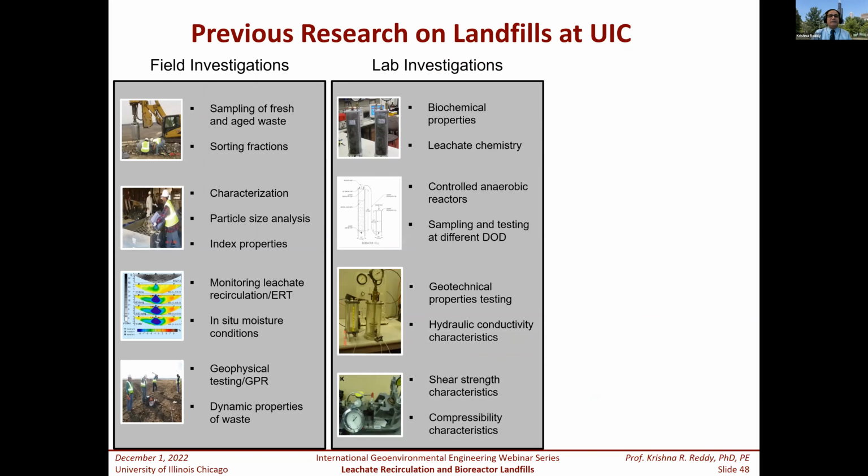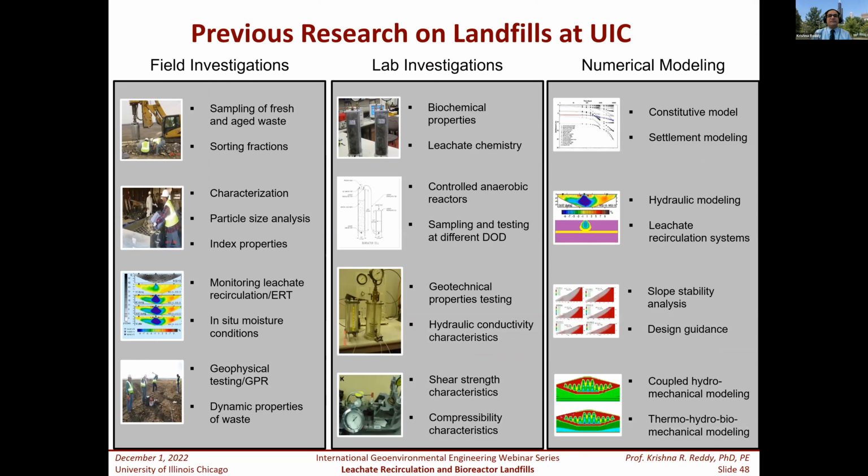In our lab, we have done a lot of field investigations. We did lab investigations. We did a lot of numerical modeling. I could talk about all these things forever, but I chose to talk only, in general, about what a bioreactor landfill is, and how it is different from a conventional landfill. I want to mention one thing again, okay? You don't want to think about a bioreactor landfill if you don't have a well-engineered landfill with the liners and leachate collection systems and the final cover system.